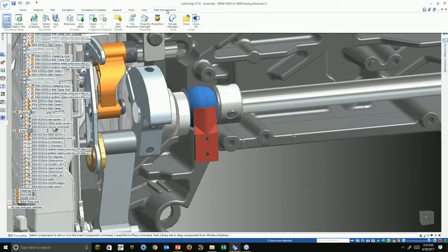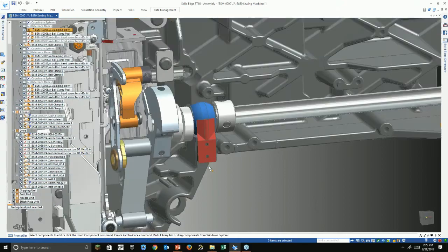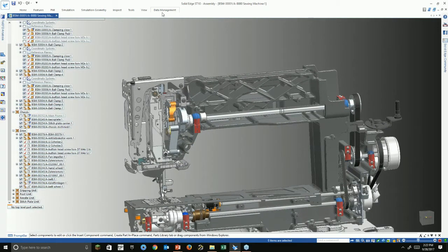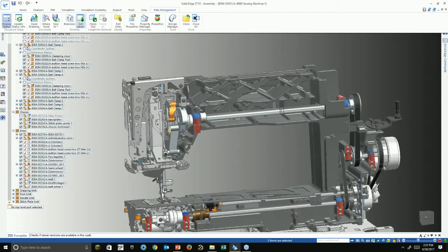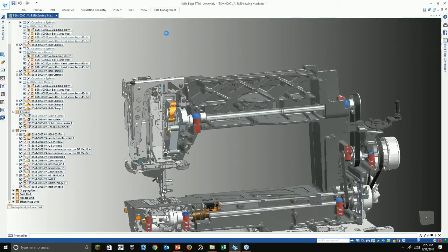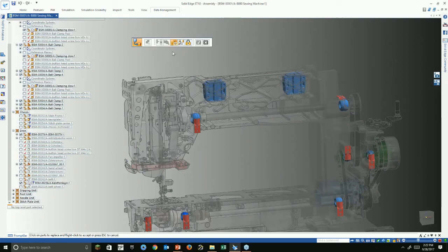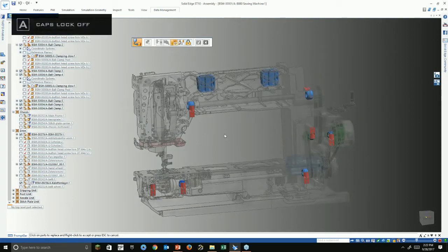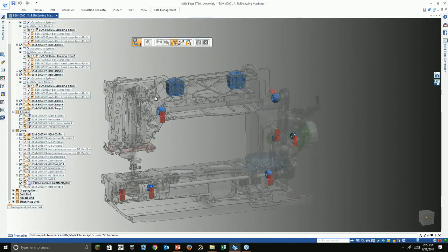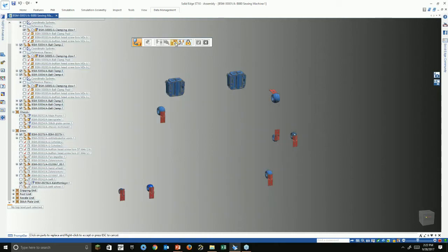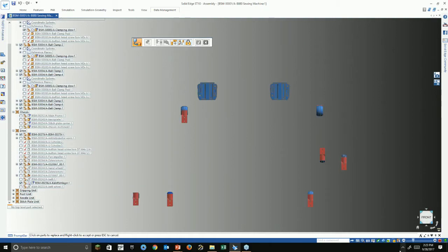All right, so what we're going to do is tell it to go through this assembly. Zoom out here and say, go look for newer parts. So, get latest releases of my parts. It's going to scan through there, and you notice it ghosts the image of parts that aren't needed. You don't have to show those if you don't want to. You can easily turn off your ghosted parts with this dialog. At any given time, just a little FYI, down here in the lower right-hand corner is all your view locations and abilities to turn different views off and on.